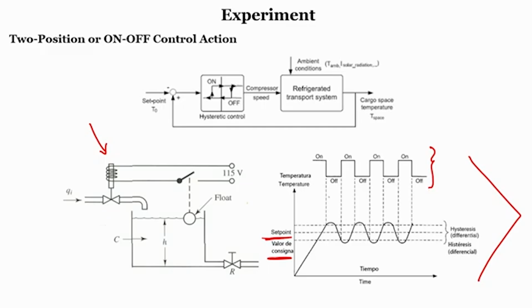It will switch off when it is above the set point, as you can see here, and when it goes below the set point, here it switches on. So, this on off action is continuous whenever the temperature is below or above the set point, and we can work on the on off control action of the circuit.